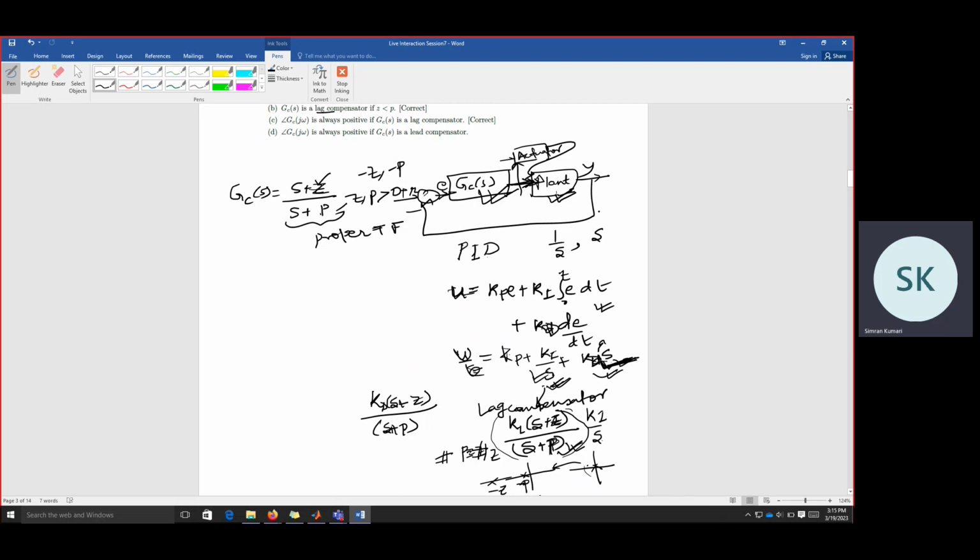And when we are including feedback, this can be done using open loop also. So we'll just have a plant, and we have some controller, you can say Gc(s), and we have input and output. Basically, controller here means some extra added components, a subsystem, such that plant behavior is modified. Now here at the output, we are not taking feedback, so this loop is not there.